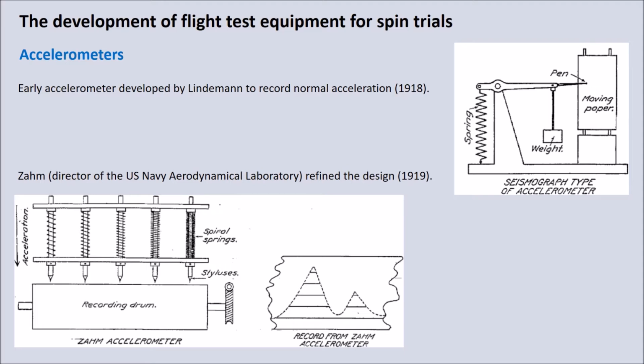The disadvantage of this though is that the resolution of the trace is only as accurate as the number of styluses and the spring constants of that setup. So depending on how the instrument was set up, and the number of styluses, it starts to get very impractical the larger this apparatus becomes.